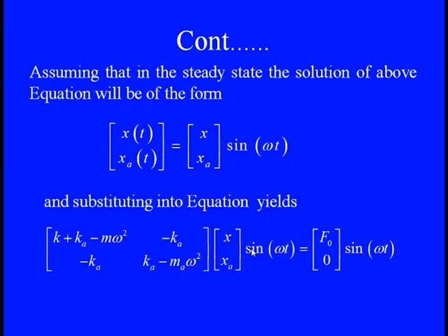When we put these things in, we know the entire steady state solution can be assumed along with the particular integral solution of the ordinary differential equations. So we have x1 and x2 with X1 and X2 times sin omega t, and when we substitute these harmonic solutions, keeping the steady state feature, we know that (minus m omega square plus k) into X is giving us F sin omega t.